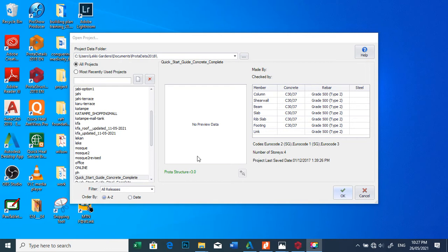The first thing you need to ask yourself before you decide on pile design is two things that will determine whether you are using pile design or not. One, the bearing capacity of the soil. If the bearing capacity of the soil is not good, so that even a raft foundation will not sit well on such soil, then the next foundation to do is piling, taking your foundation below the soil to get a firmer soil.